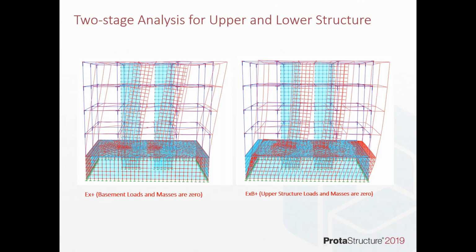Now, another key consideration of seismic design is that often you'll have basements, and these need to be treated differently. We will do a two-stage analysis for the upper and lower structures, looking at different R factors for above and below, and automatically combining those for design.